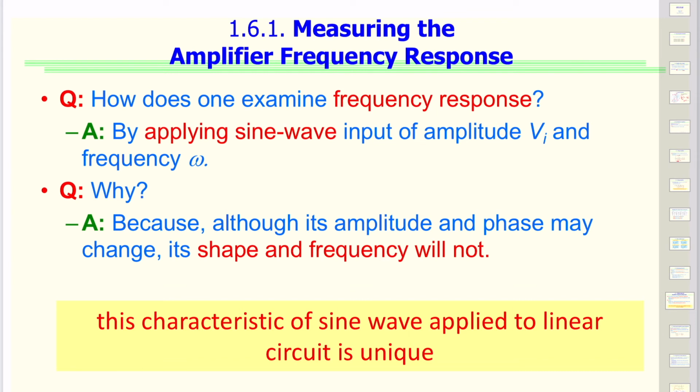And this is the reason many times we just analyze an amplifier on one frequency, because we have already removed the other frequencies, or we are focused on a very small band of frequencies. And to measure the response of an amplifier, we can apply white noise. So we can apply a signal which has a bunch of frequencies, and that can help us see that only the frequencies that we have designed it for are showing up on the output.